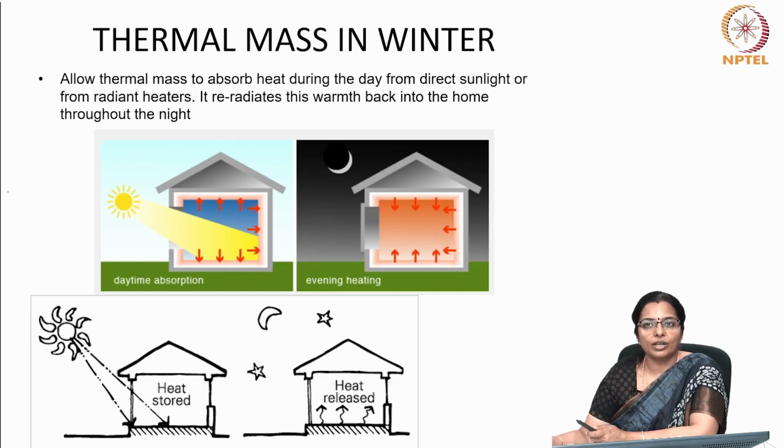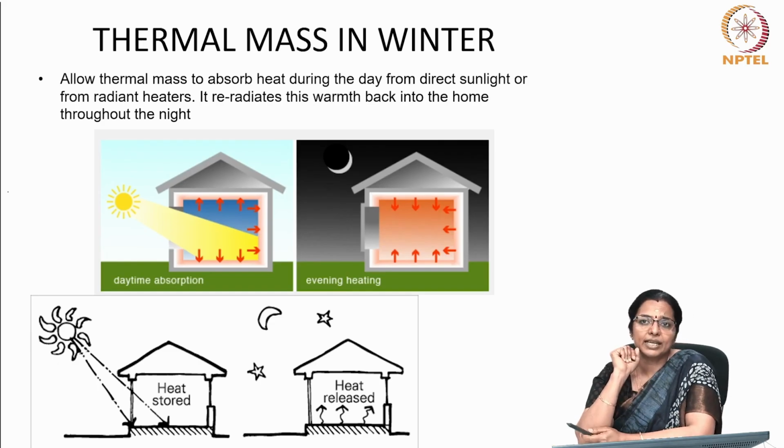In warm or hot climates where there is significant temperature variation between day and night, also called diurnal variation, heat is absorbed during the day and then released in the evening, when the excess can be either flushed out through nocturnal air ventilation or used to heat the space as the outside temperature drops. The entire process can thus be repeated the next day.